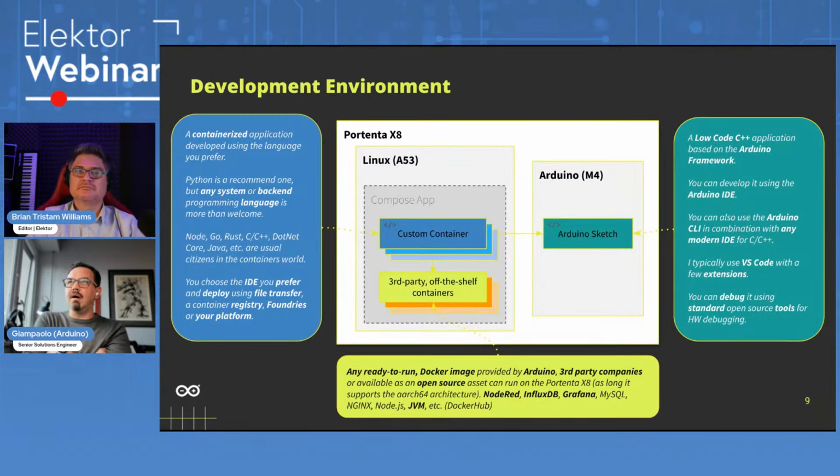The rationale for this is that you can decouple the real-time, difficult part, in C++ or MicroPython, to be run on the Arduino side, and have more complex applications on the other side, for example displaying data over an HMI panel, or exposing a web server with a graphical user interface for showing the data, having dashboards, or interacting with more complex systems, something that can be difficult to do in Arduino itself. And on the other side, you have stuff running in real time in the Arduino Sketch.